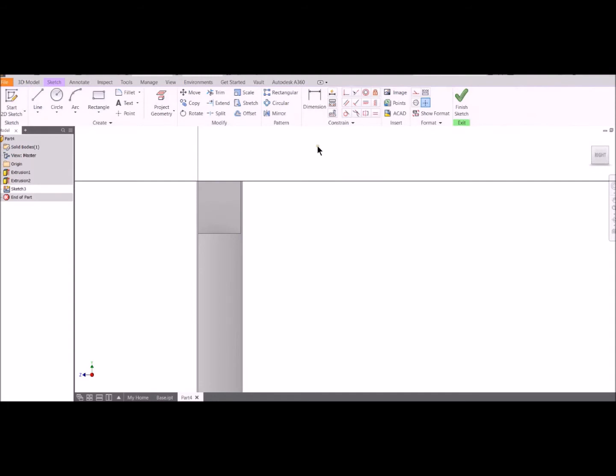I'm also going to drill that 1/4 inch hole through the middle of it too. So again, I'm going to turn on my construction line, and this is just to center that hole. So I'm making a 1/2 inch long. Now, it's not going to be exactly a 1/2 inch long diameter, because we're not going through the center of this thing. We're just a little bit off center as the working plane we're on, but we can at least center it on that little cutout. Okay, so here is our 1/4 inch hole that we can drill through it, and this should fit into there.